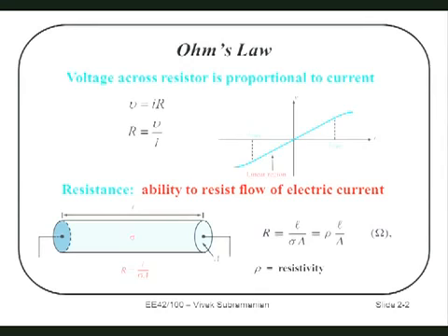Okay, now let's take an example. Those carbon film resistors that you were working with, let's say I give you 2 resistors. They're nominally identical. All those resistors you were dealing with in class were nominally about the same size, right? How do we vary the resistance? If they're about the same length and about the same diameter, how do we vary the resistance? Sorry? Well, but to do that, it would make it longer, right? If I was putting material in series, wouldn't it make that resistor longer? Okay, so I want to keep the resistor the same size. Sorry? Use a different material. That's the right answer. That's actually what they do.